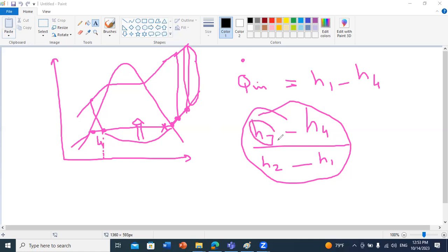H1 will not be affected, so you will keep a high enough value for W. This will not affect the efficiency in a bad way. So you will be able to increase the extracted heat while not increasing at the same time the W dot required for the compressor.